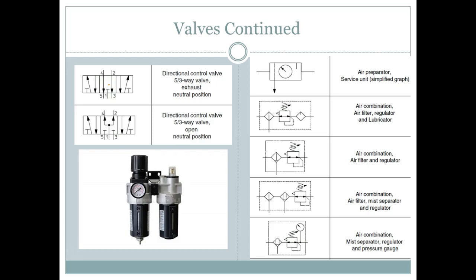Otherwise you'll lose it, and then when you shift it over, you'd have to wait till it recompresses. A hydraulic pump, though, is creating flow, and you've got to understand these guys don't create pressure unless you work them against something, right? So that's what we do with pneumatics. We work it against the whole system itself. Hydraulic pumps, though, you've got 2,000 or 3,000 psi available to you on that sucker if you regulate it.